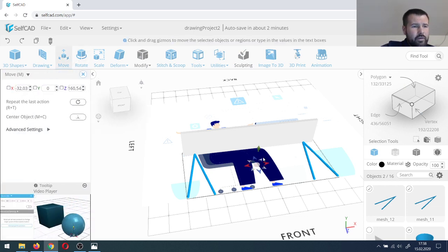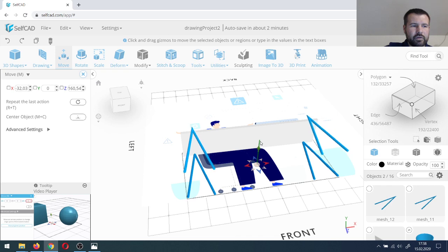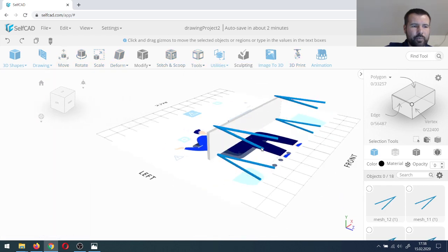And what I'm going to do to actually generate the remaining legs is using copy drag. By holding Ctrl while the move transformation is enabled, I can move and copy at once just to create copies that are already on a different dimension than the original ones.